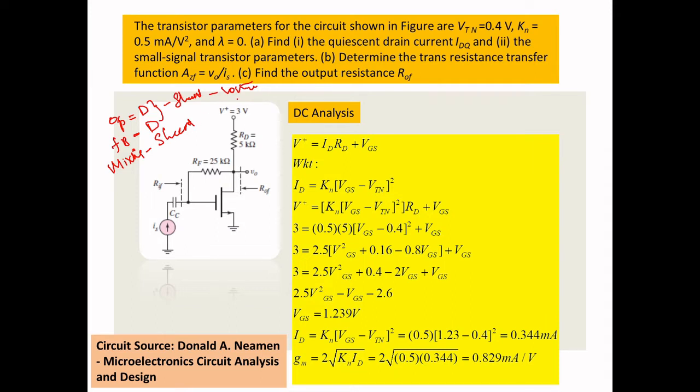By looking at the circuit, you can identify it easily. This is a shortcut method to identify any circuit, and it will be very useful. So this circuit comes under voltage shunt feedback, that is the shunt-shunt or transresistance amplifier. Your output will be voltage and input will be current. I hope you understood.